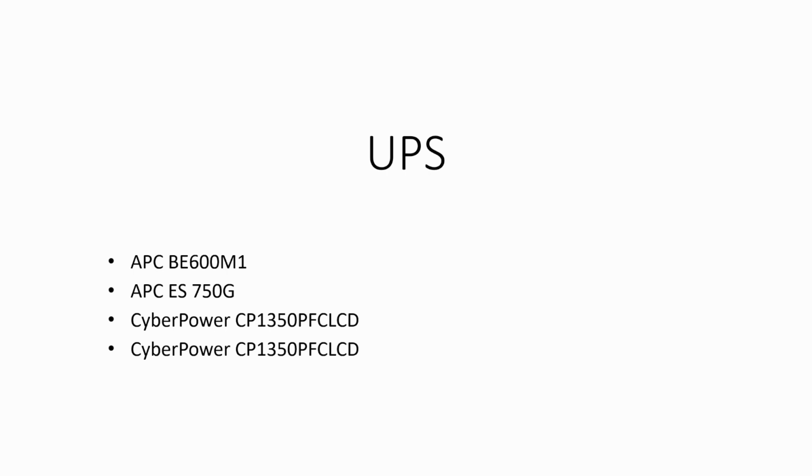Now, you have to be careful in how you select UPS. Number 1, you want to make sure you go with the major vendors like APC, CyberPower, because normally they work better. Number 2, you want to make sure they have a USB interface. This is very important. They must be having a USB interface. And also the hardware to which it is attached must have a USB interface. So we'll come to that later, why it is necessary, right?